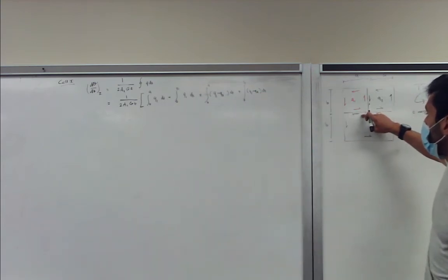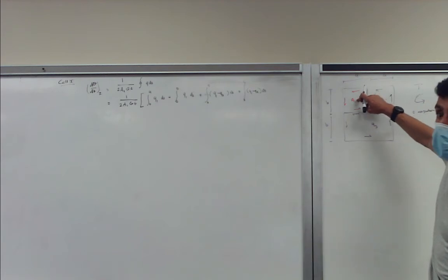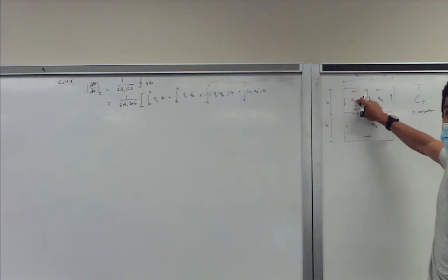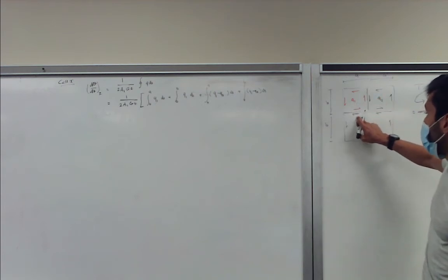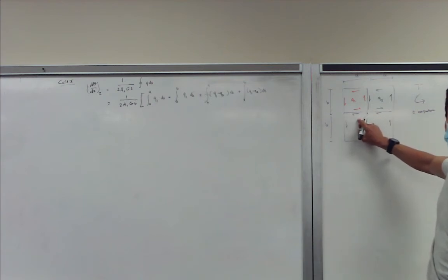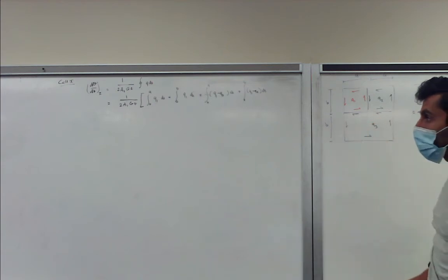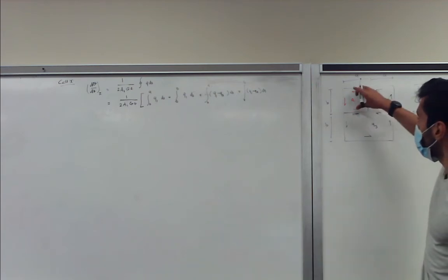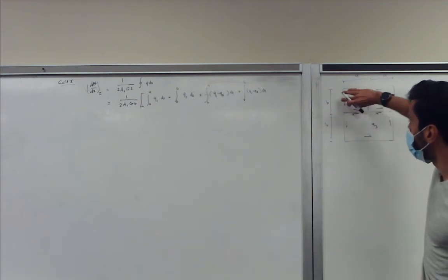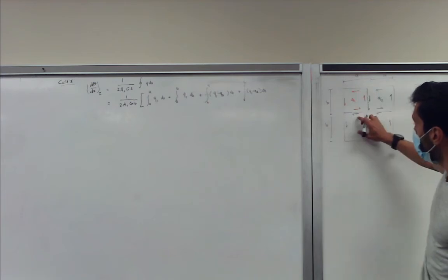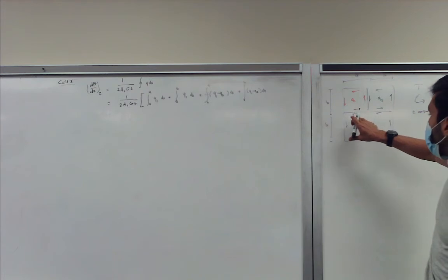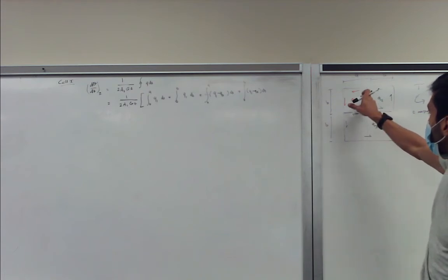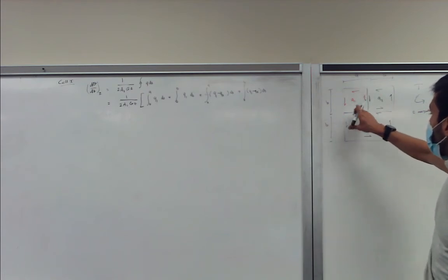Because even though this is cell 1 and has a constant shear flow and a constant torque to it, and therefore constant shear flow due to that torque of cell 1, cell 3 has an effect because they share the same wall. So if you take the rate of twist, you have to think about it: cell 1 wants to deform it counterclockwise, and this cell basically tries to stop it by deforming it in the opposite direction.